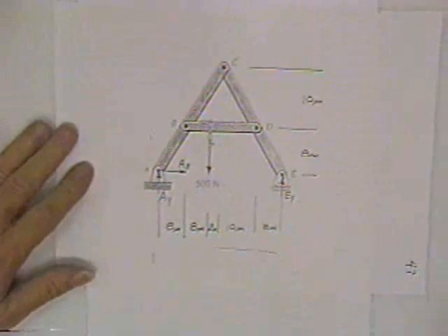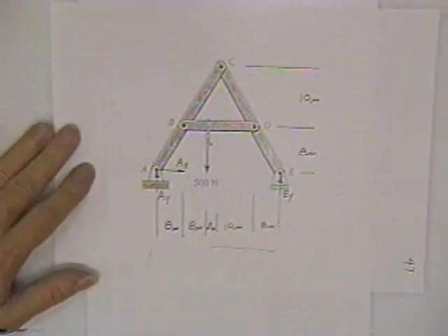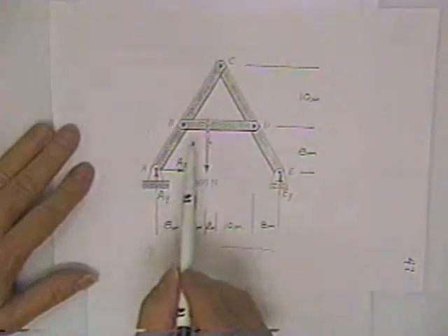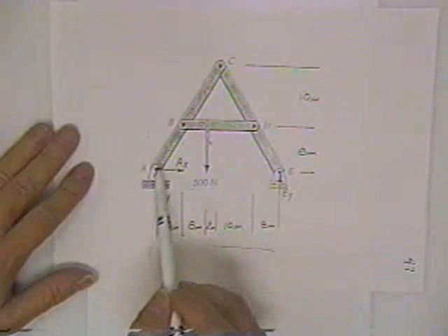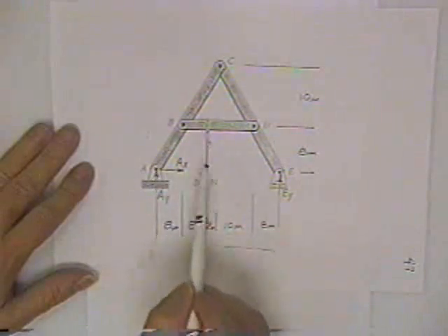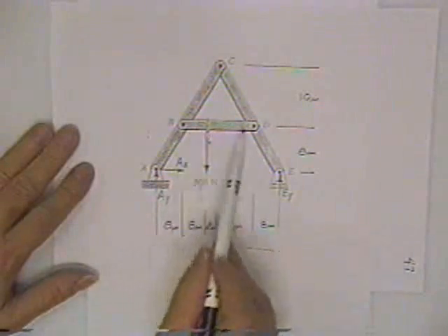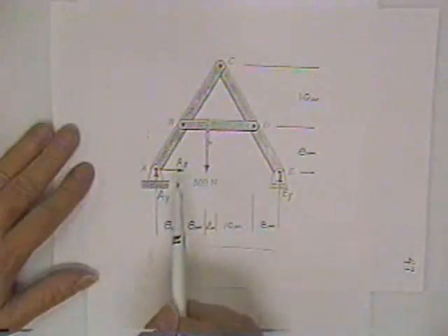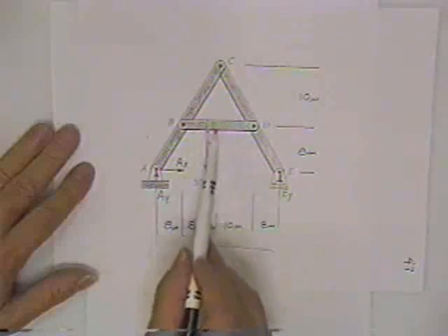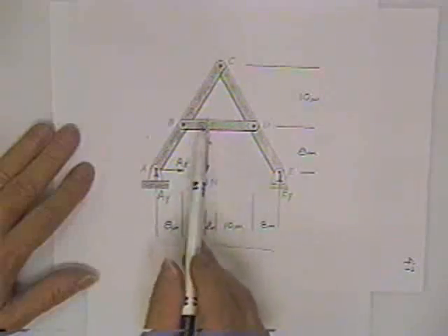The last thing we'll do are frames. Frames are pieces of steel. Unlike a truss, a frame can have a load in the middle of a member. A truss never has a load in the middle of the member. It would collapse immediately, because the members are not strong enough in bending to resist that. So rather than being a nice slender piece of steel here, this is probably a 2x4 or something like that.